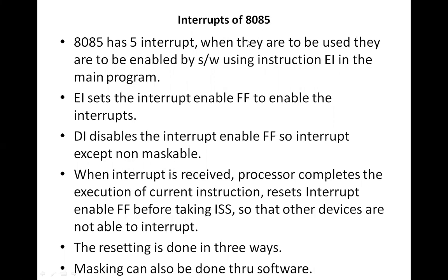Whenever an EI instruction is used within the main program, after the execution of that instruction, the flip-flop will be enabled and the microprocessor can be interrupted by any device connected through these interrupt lines.